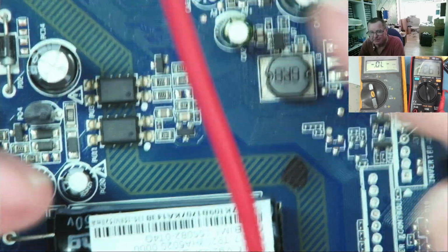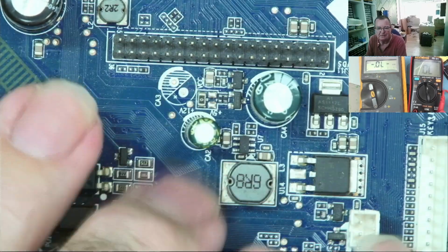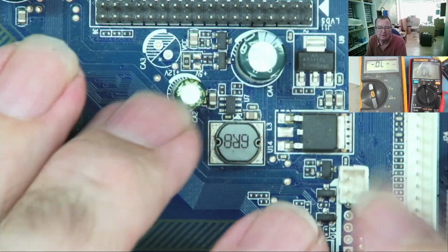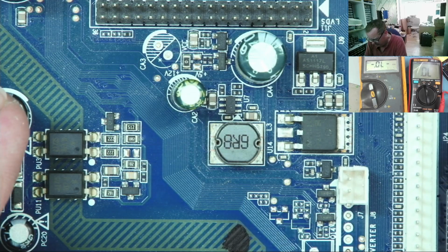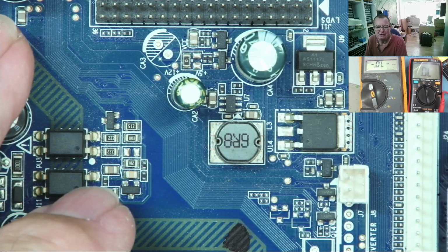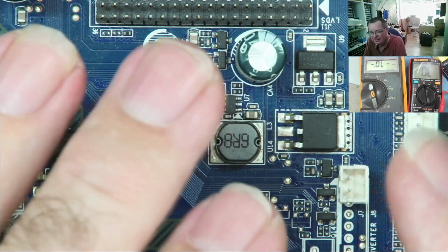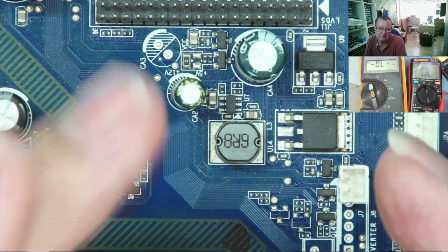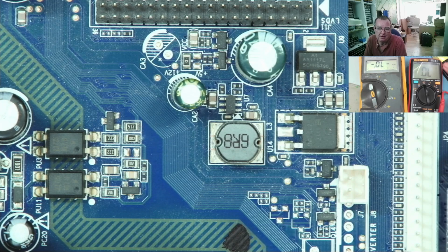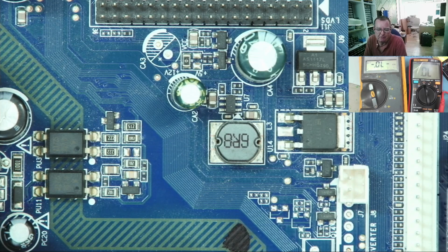So when I said that you can only test these things out of circuit, I wasn't being quite honest there. I wouldn't say I was being dishonest, it just wasn't quite telling the whole story. You can test transistors in circuit using two meters, both in diode mode, and that's a really useful thing to know when it comes to fault finding.